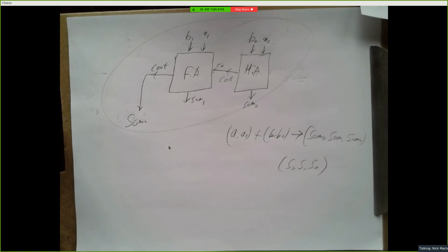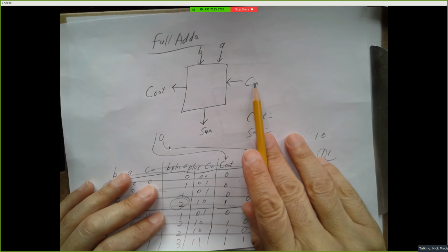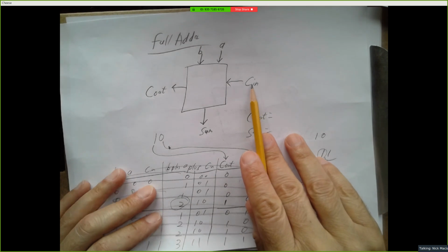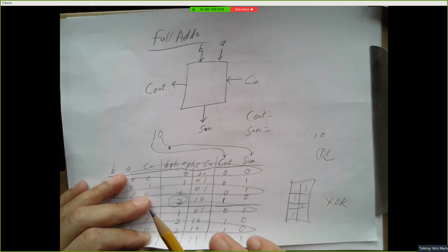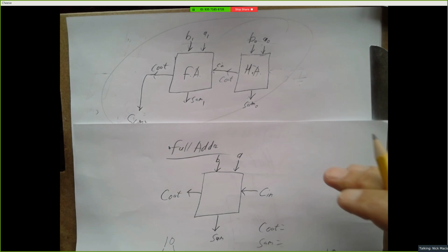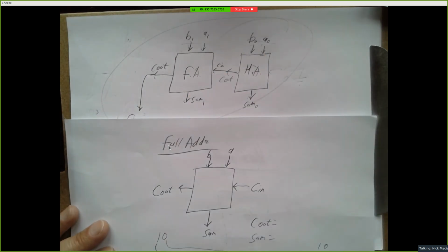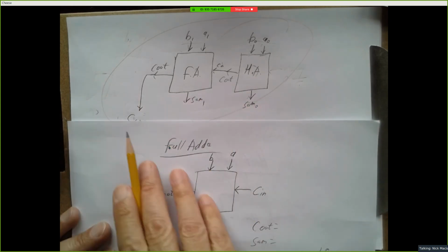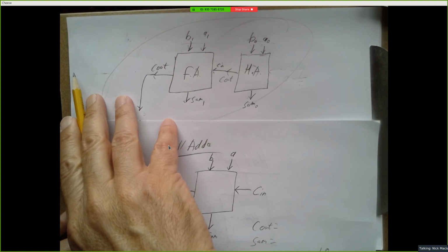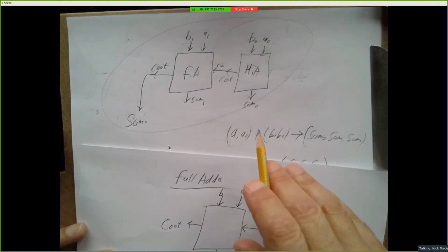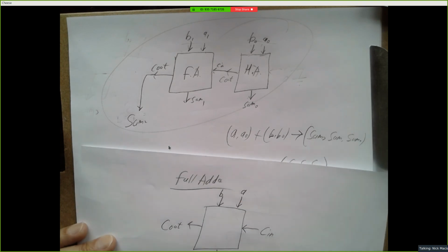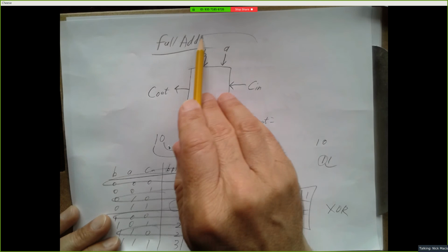Does this only work for the 3 inputs you have? So a full adder is specifically a 3-input, 2-output device, right? But we could use it, for example, to add numbers A and B, where those had 4 bits each. We could string 4 of these things along. We could feed the 4 bits of A into the 4 adders, and the 4 bits of B into those 4 adders. And we would get 4 sums and a carry out. That's a 5-bit final answer.